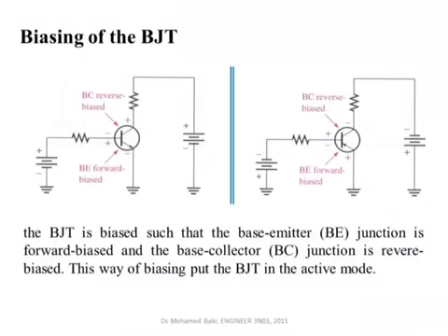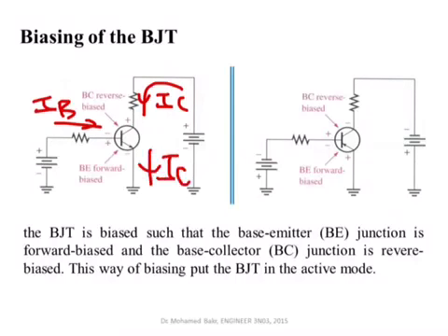The same thing is also happening for a PNP transistor. First for NPN, this is the direction of the collector current. This is I collector, it's flowing in. This is the direction of the base current, a much weaker current, and this is the emitter current. You can see the arrow direction indicates the direction of the emitter current. For a PNP, we use different polarity here.